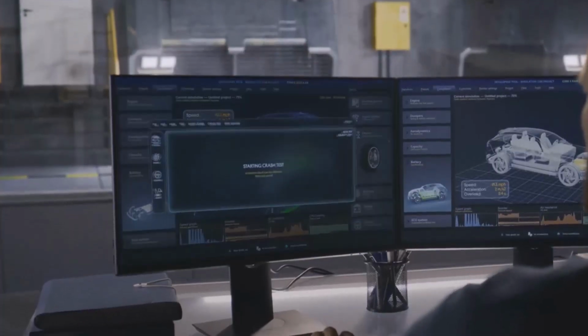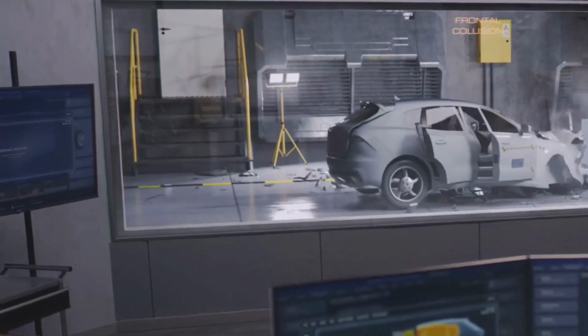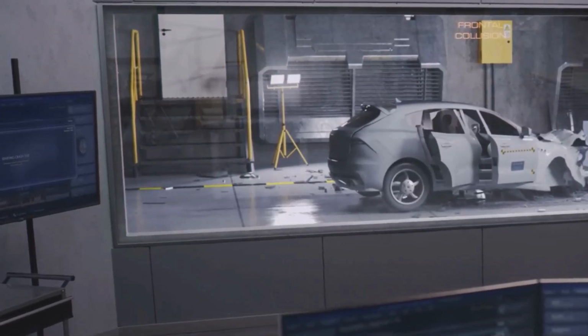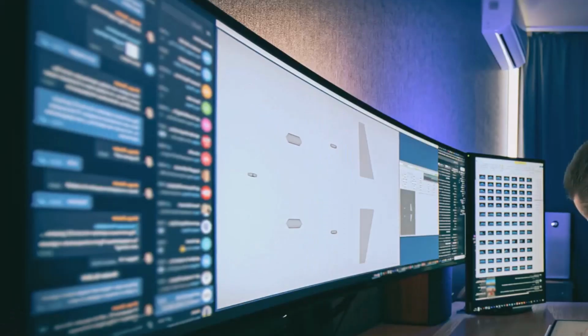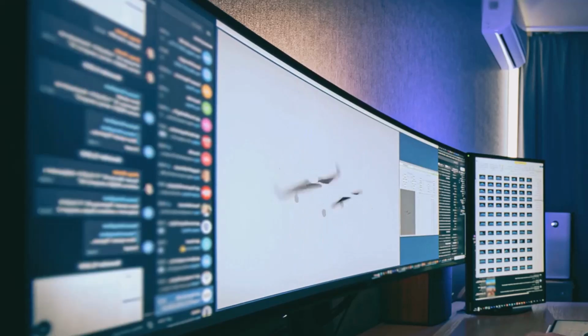Think of it like trying to watch a movie. If you're watching a high-definition movie, you can see every single detail, every eyelash, every tiny expression. That's like having a Y+ value of 1. Your computer simulation is capturing all the fine details of the flow right at the surface. However, if you try to watch the same movie in very low resolution, all those details become a blurry mess. You can get the general idea of what's happening, but you miss the important nuances. That's what happens when your Y+ value is too high. Your simulation misses the crucial physics at the wall.